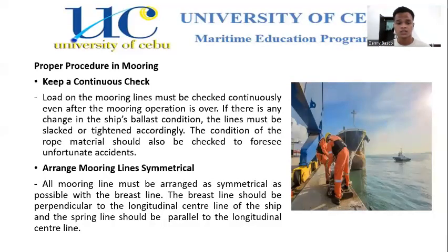So next is arrange mooring lines symmetrically. So all mooring lines must be arranged as symmetrically as possible with the breast line. So the breast line should be perpendicular to the longitudinal center line of the ship, and the spring line should be parallel to the longitudinal center line.